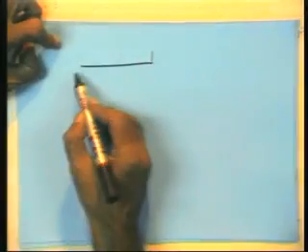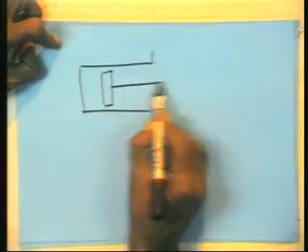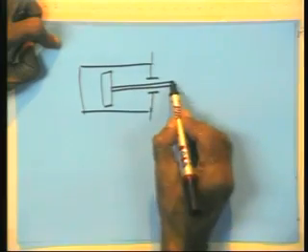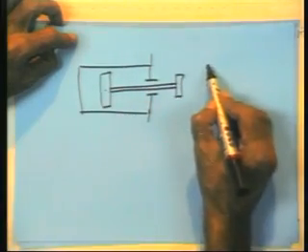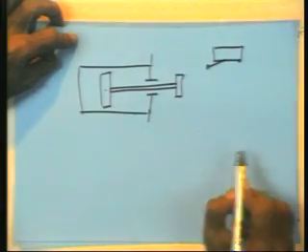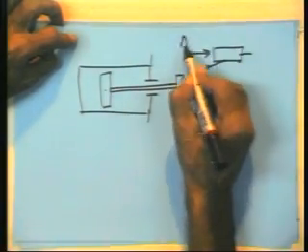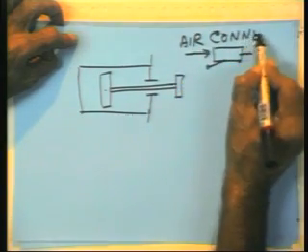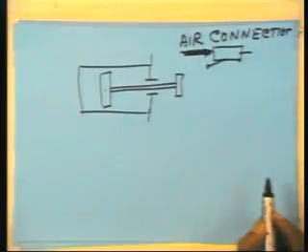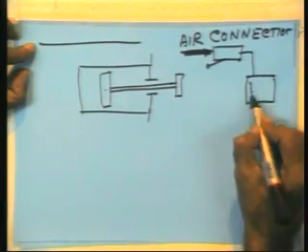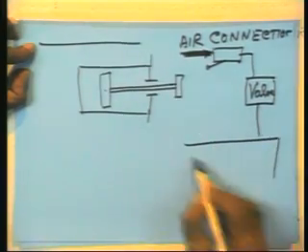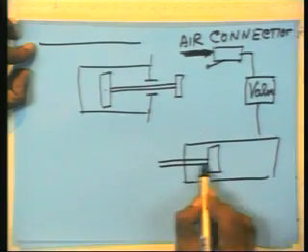For example, what you could do is, when the cylinder motion is completed, here usually the word used is, you always think of the piston moving, but the terminology used by the industry is cylinder motion. Supposing this has hit this, then it might trip a limit switch. There is an air connection here to this limit switch. You have a pressure line, an air line going here, that you connect to the limit switch also. When the limit switch is hit, this in turn will operate the actual valve, which in turn will operate the next cylinder. So these are the pilot valves.